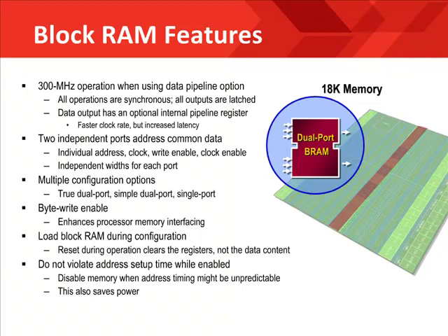The block RAMs include a configurable aspect ratio functionality, which allows each block RAM port to have a customizable width. This helps the memory lend itself to more applications and ensures efficient use of the block RAM. For example, this means you can write to port A in bytes, plus the parity bit, and then read from port A serially with no access to the parity bits, and also write to port B in 16-bit words, plus 2 parity bits, and then read from port B in 32-bit words plus 4 parity bits. There's simply put quite a bit of flexibility with this configurable aspect ratio that the block RAM has.